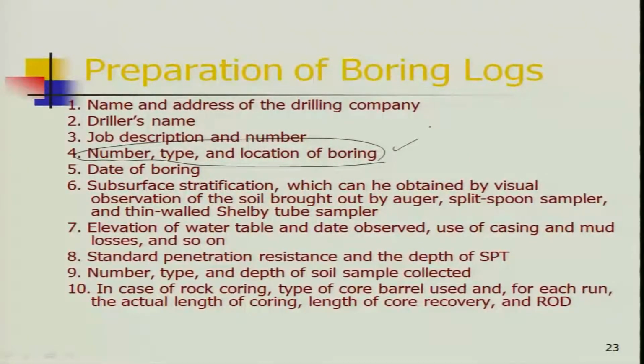How many boreholes, the type and location of the boreholes, and the date of the boring. More important is the subsurface stratification. Stratification means any depth-wise variation, and that has to be shown. It can be obtained by visual observation of the soil brought out by the auger, split spoon sampler and thin-walled Shelby tube samplers. Also the evaluation of the water table and date observed, use of casing, and so on.